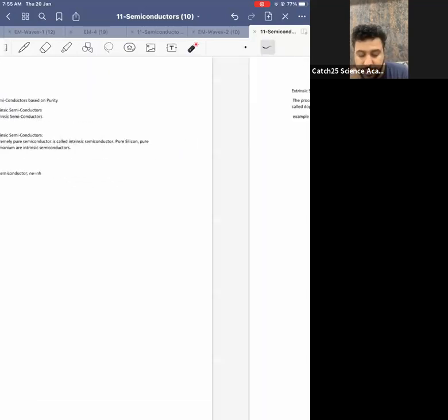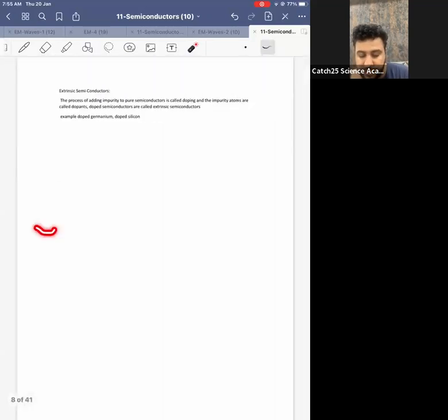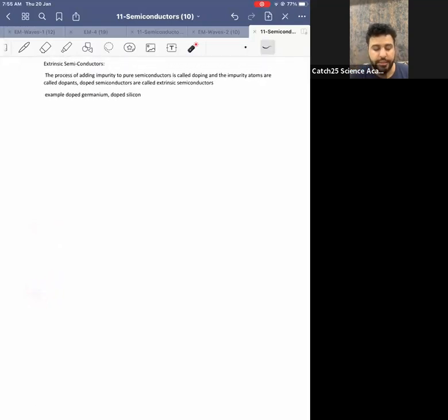Therefore, if you look at the definition of extrinsic semiconductor, look at the screen. The process of adding impurity to semiconductor is called doping, and the impurity atoms are called dopants, and doped semiconductor is called extrinsic semiconductor.